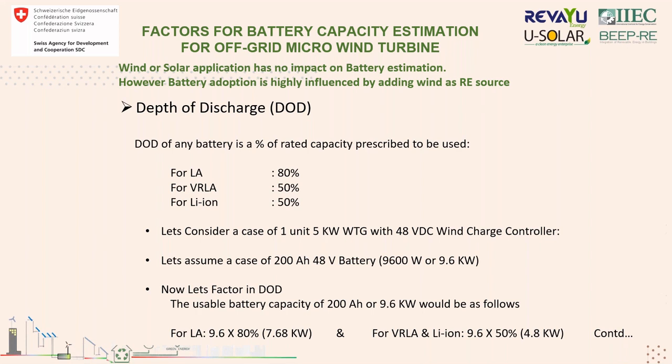So the most important factor which one should consider, other than cost. Commercial people consider cost, but for technical people who are designing, the depth of discharge of the battery is the first thing that they should notice for designing, because you will come across this figure, which is 80% or 70% or 85% or 50%, as the depth of discharge of that battery bank. That's the prescribed.